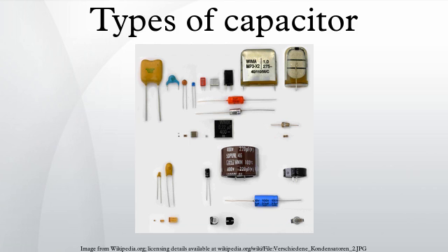Additional information, soldering. Capacitors may experience changes to electrical parameters due to environmental influences like soldering, mechanical stress factors and humidity. The greatest stress factor is soldering. The heat of the solder bath, especially for SMD capacitors, can cause ceramic capacitors to change contact resistance between terminals and electrodes. In film capacitors, the film may shrink, and in wet electrolytic capacitors the electrolyte may boil. A recovery period enables characteristics to stabilize after soldering. Some types may require up to 24 hours. Some properties may change irreversibly by a few % from soldering.